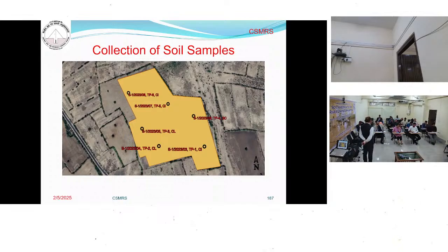At least you should know the names. This is what it is for. This is PRT. This is the limitation, and these are the things. You should know only because you are not going to conduct that. But at least you can suggest when you are dealing with the project, you can say, sir, SPT cannot be done here, because the strata contain gravels and boulders. Other tests can possibly be done. So you should have that much knowledge.